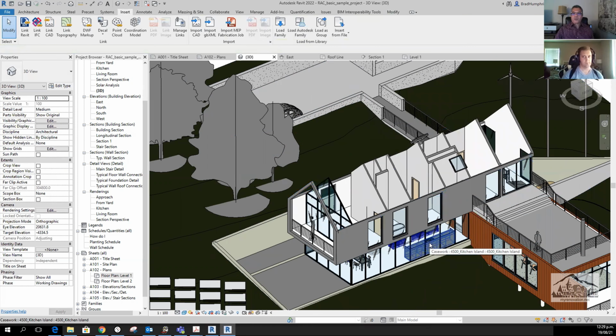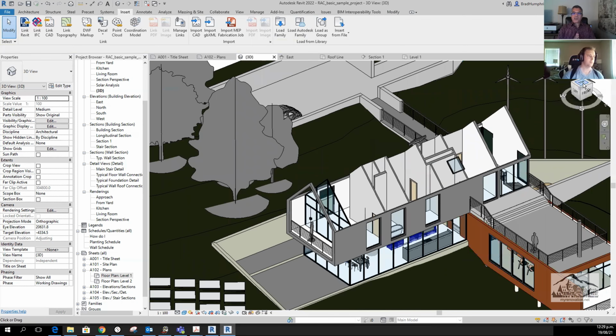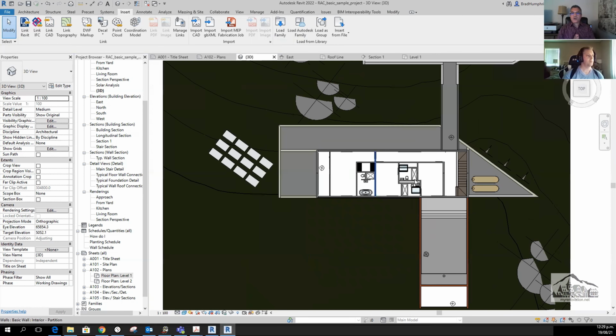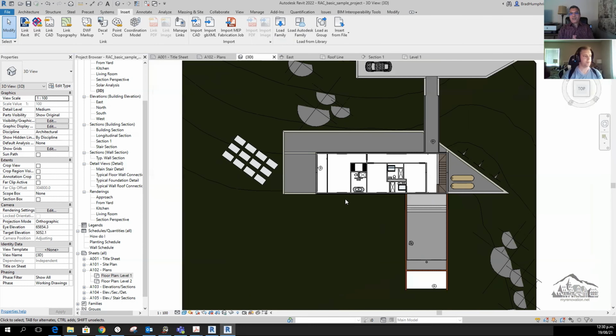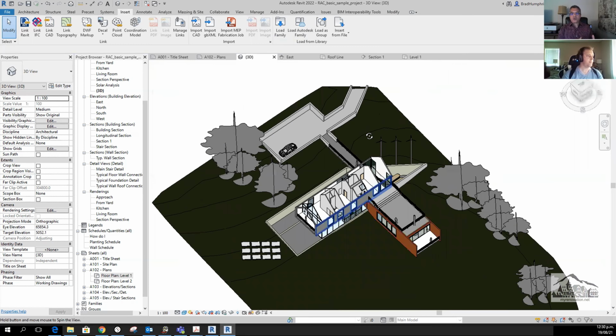Yeah, I just want to explain something, like the way actually as architecture project manager, we use this software. The first thing we do is we create something we call the base model. This base model will have all the walls, the fixtures, the roof, and the foundation. And then we take this base model and send it to our consultants.